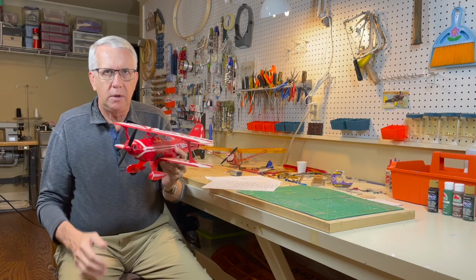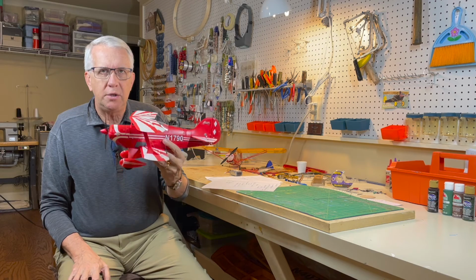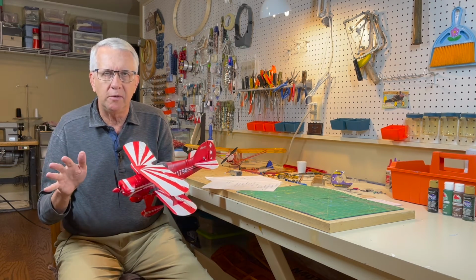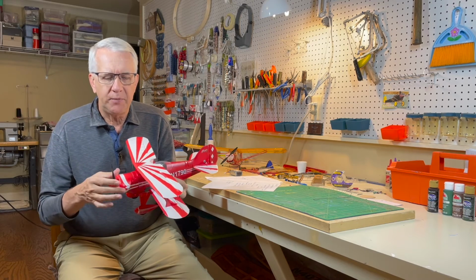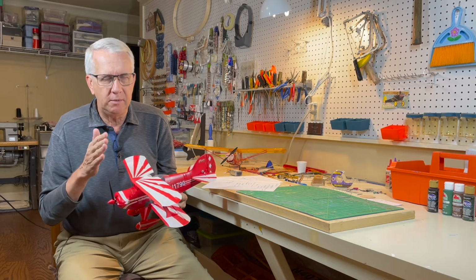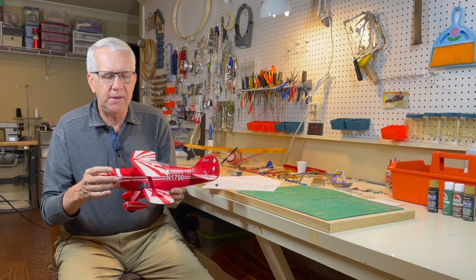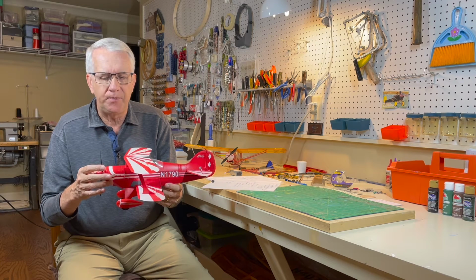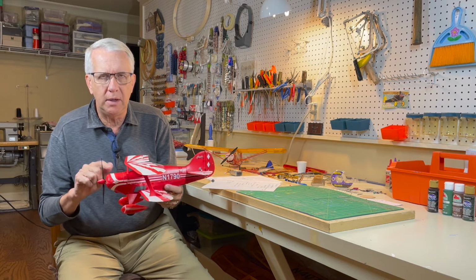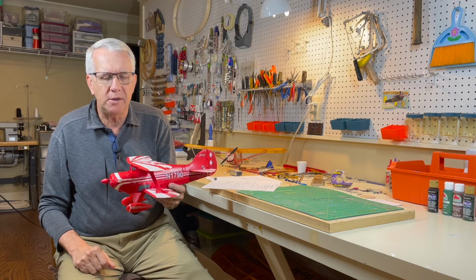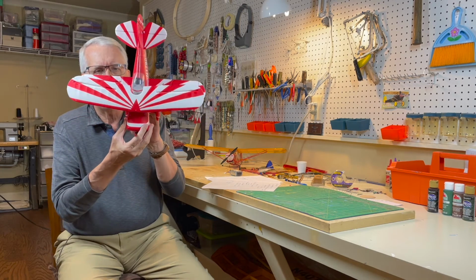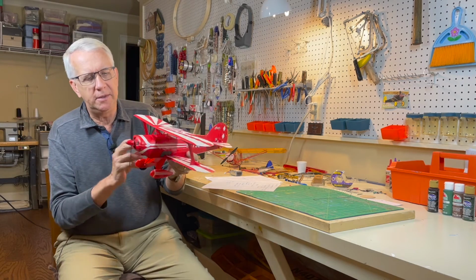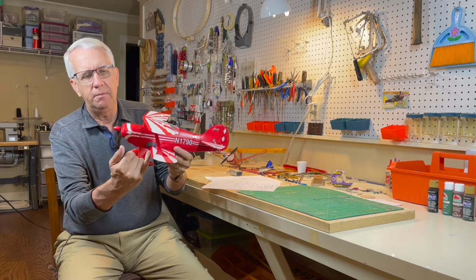I'd like to point out also that every aircraft has a center of gravity location, to include almost-ready-to-fly models. Back in the days when we were building our own models from kits and from plans, the center of gravity was just something you had to do. Very often these kits, just about all the time, come out of the box with everything designed for the proper center of gravity, again with the battery installed. But notice also in this biplane, there's a very slight sweep to the leading edge of the top wing. This would be a little bit complicated, and then there's a stagger between the leading edge of the front and back.